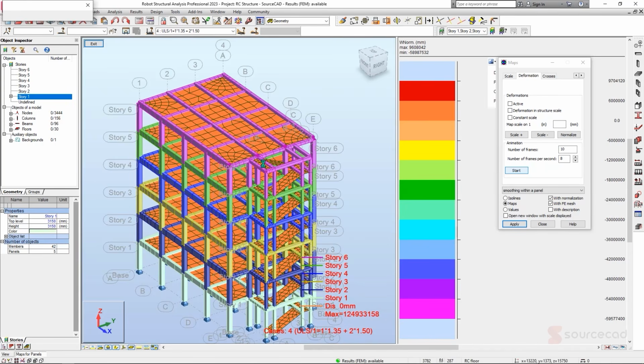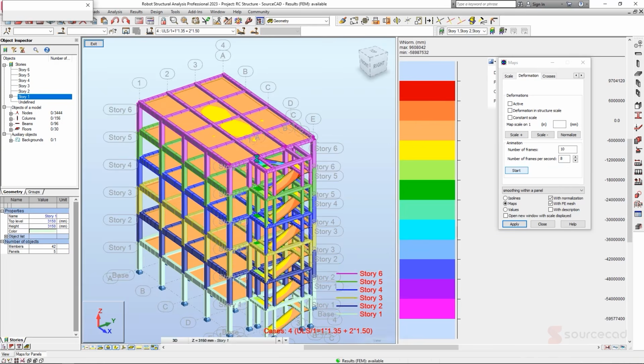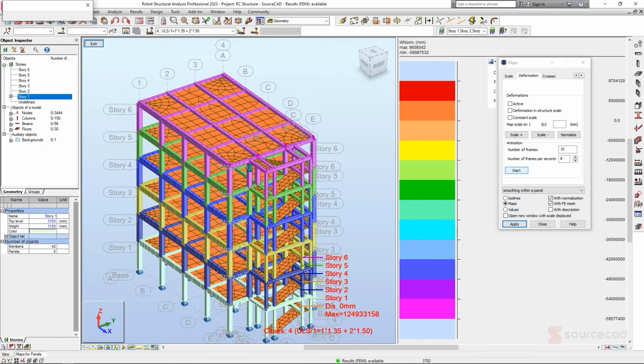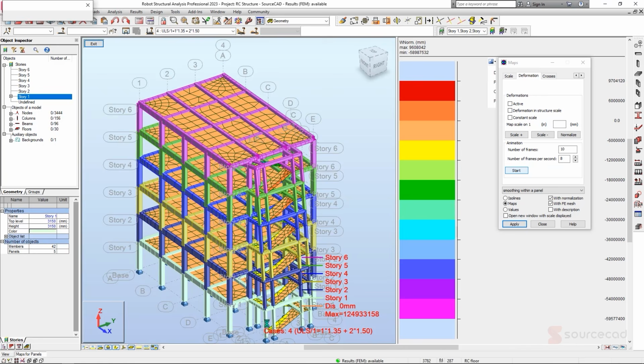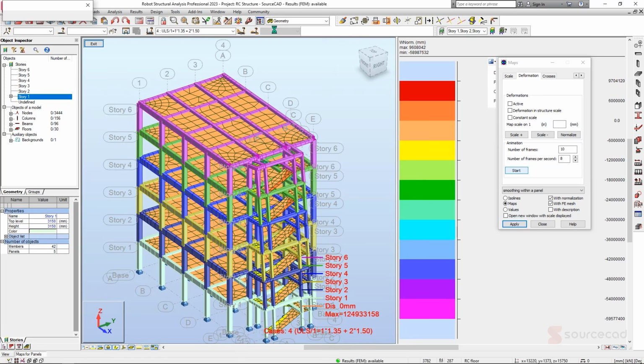Alright, so from our analysis, you can clearly see that the connection of our beam structure here has not been done. That's why the sway is just making it fall all the way down, as well as this member down here. So we can resolve this quite simply by going back to our model and doing a proper connection of these 2 points here.